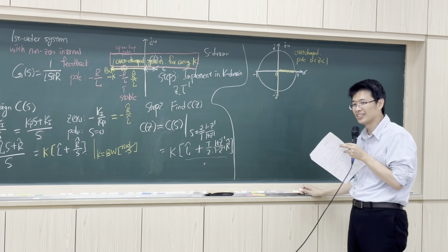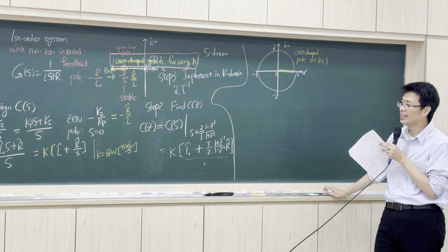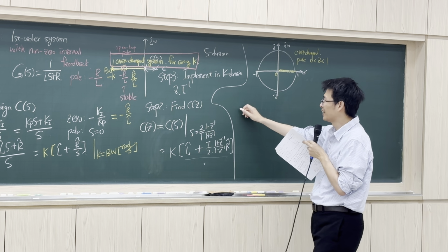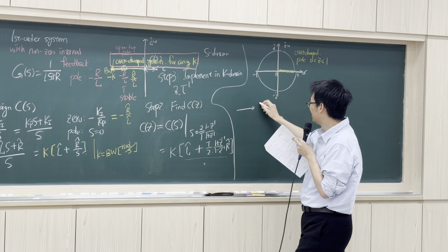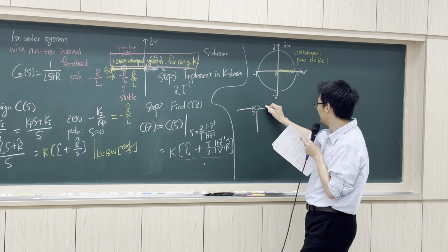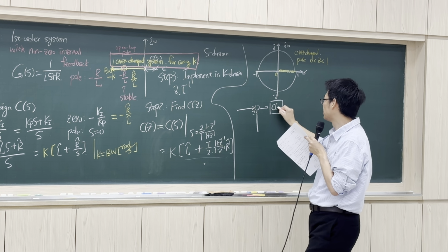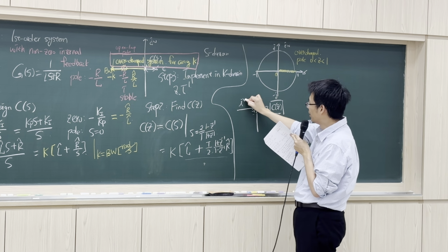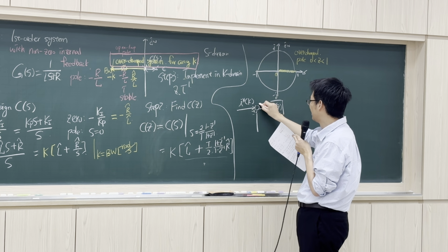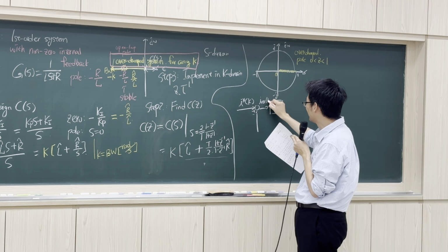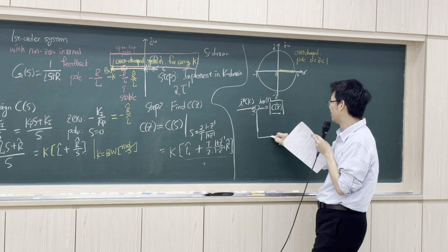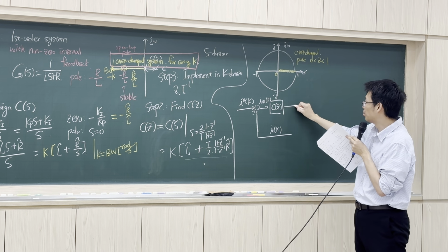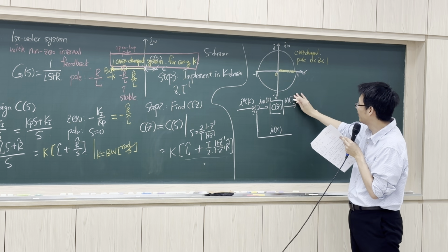Okay, so right now we can check our controller design performance actually in discrete time, not in continuous time, because this is just a linear approximation. For the overall discrete time system, it is similar to that one. We have a controller C(z). Right now the input will be our current error, based on the comparison between our command and the measurement. The output of this C(z) is the manipulated input, n(k).